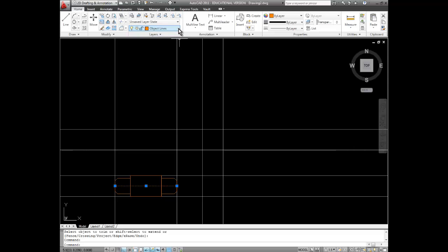So this one will be a center line. We can expand it so it goes beyond the area. So now we need to draw a line from here to here to establish our shoulder, and another one here. And that will give us our chamfer. Now we can actually draw our right hand side view or draw our top view.